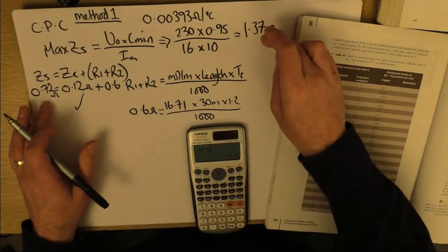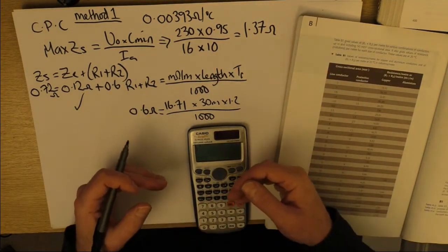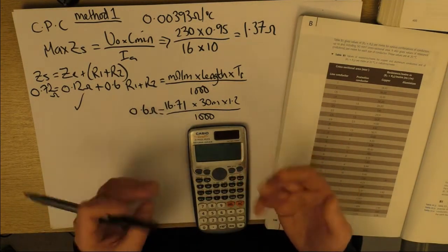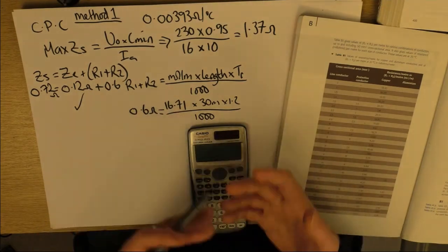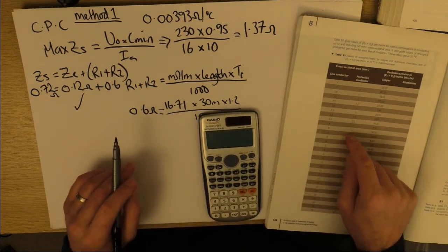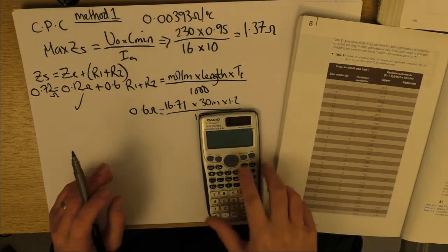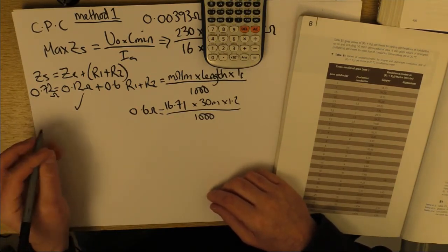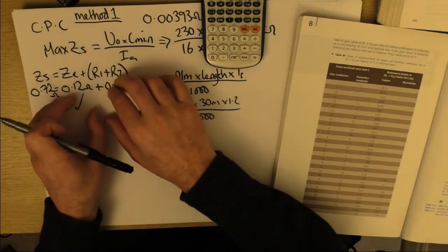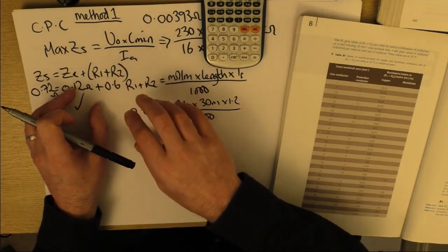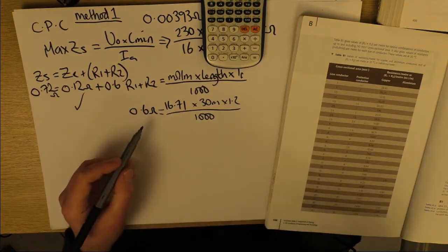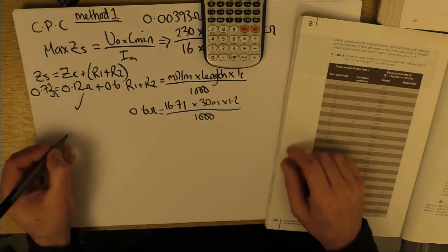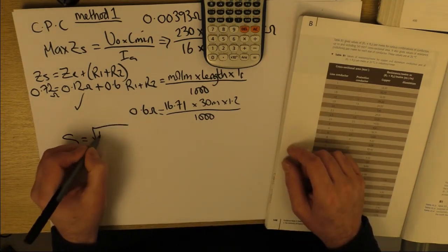And in fact, it's quite well within, so we might be able to drop it to 1 mil perhaps. But then, if you're running 4 mils, you've got to think of mechanical protection as well and things like that. So I think I'm going to stick to 1.5. And my hunch is that a 1 mil might struggle with the next bit, which is the adiabatic or the thermal constraints. So we know that it's going to generate enough fault current to trip the device, but can that CPC, the 1.5, sustain that fault current for that time until it disconnects? That's where this adiabatic comes in.